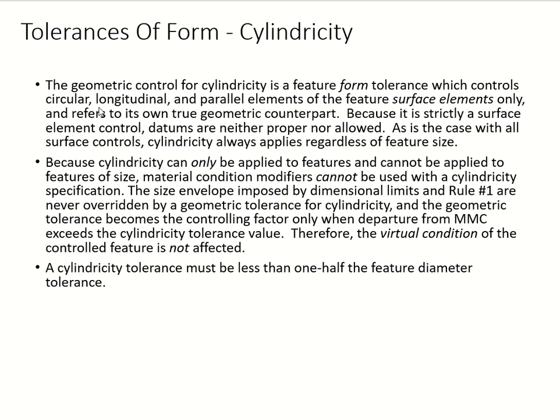We have other controls: circularity, longitudinal, parallel, yeah, on your surface elements, and we call those the geometric counterparts or geometric controls over cylindricity. And we don't use a datum. Cylindricity always applies on your RFS. We don't have material modifiers in your feature control frame.